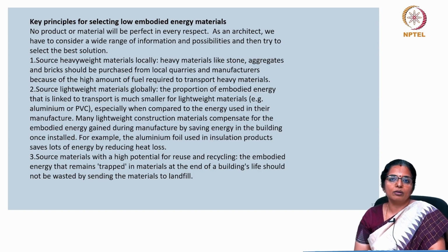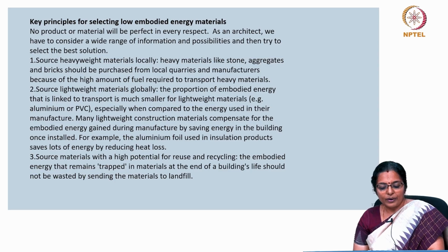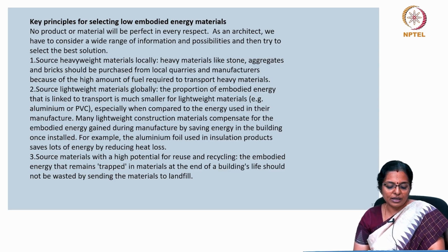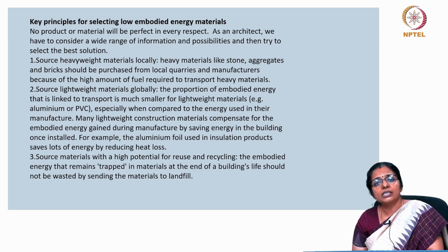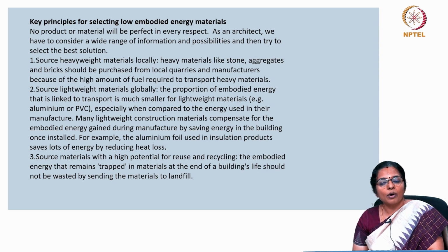For example, aluminum or PVC, especially when compared to the energy used in their manufacture. Many lightweight construction materials compensate for the embodied energy gained during manufacture by saving energy in the building once installed. For example, the aluminum foil used in insulation products saves lots of energy by reducing heat loss. So, aluminum is not to be demonized after all, because the amount of heat loss that it saves overpowers the embodied energy it actually consumes.